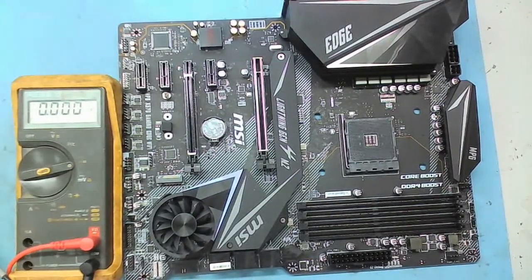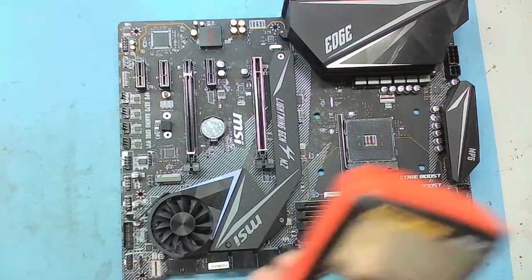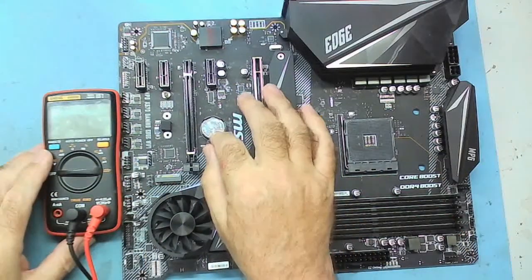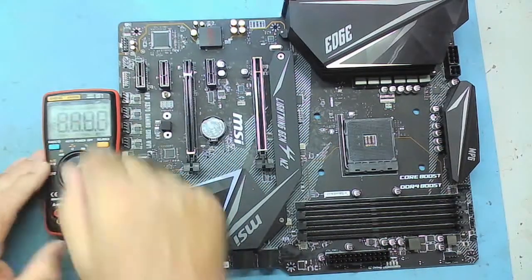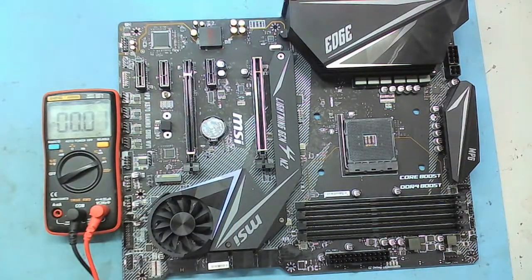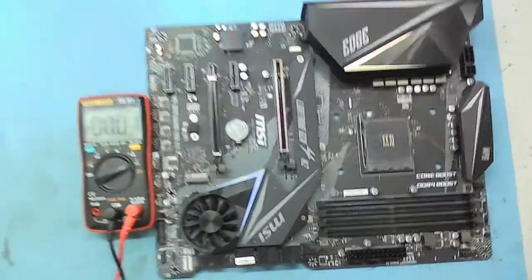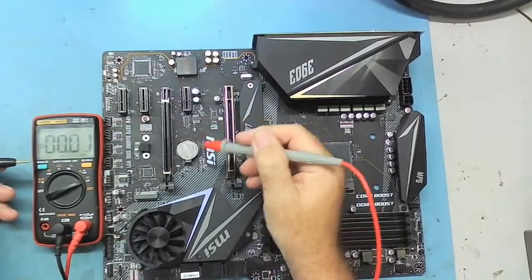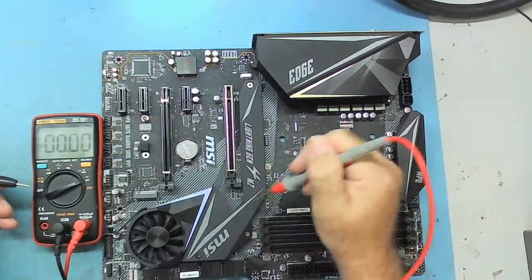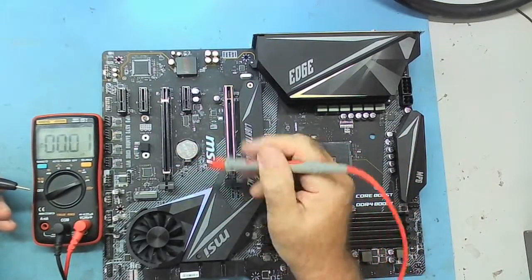Another thing I always like to check is how much current's being drawn from the CMOS battery. There's no exact right or wrong answer here, but quite often if you come across a CMOS battery that's completely drained, you'll find there's an excessive current being drawn from it. So I'm going to put this onto the milliamps, so microamps range. I'd expect, on a board like this with just the CMOS battery, that's basically powering the real-time clock. Yes, the real-time clock crystal on here is running. That's powering some part of the circuit.